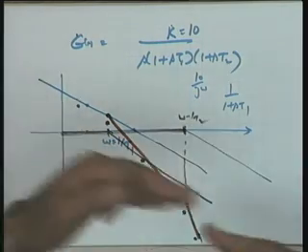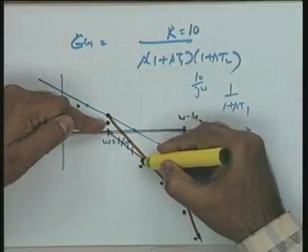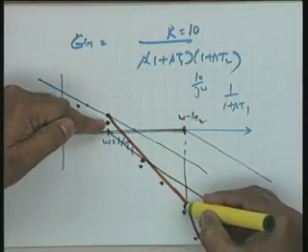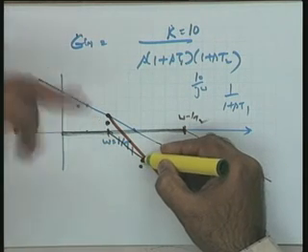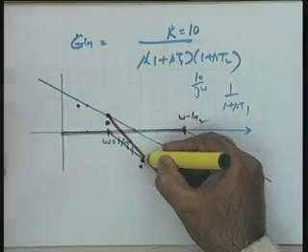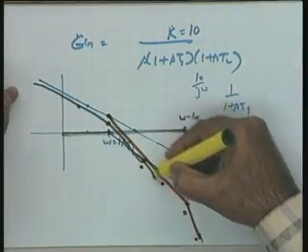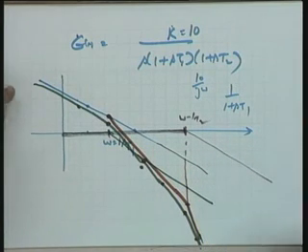Please see that it is just an algebraic addition. 1 octave above because of this factor has come over here, 1 octave below because of this factor can come at the same point. In that particular case, the net error at this particular point will become minus 2 dBs, and hence a plot passing suitably through all these points is the accurate plot of the system.